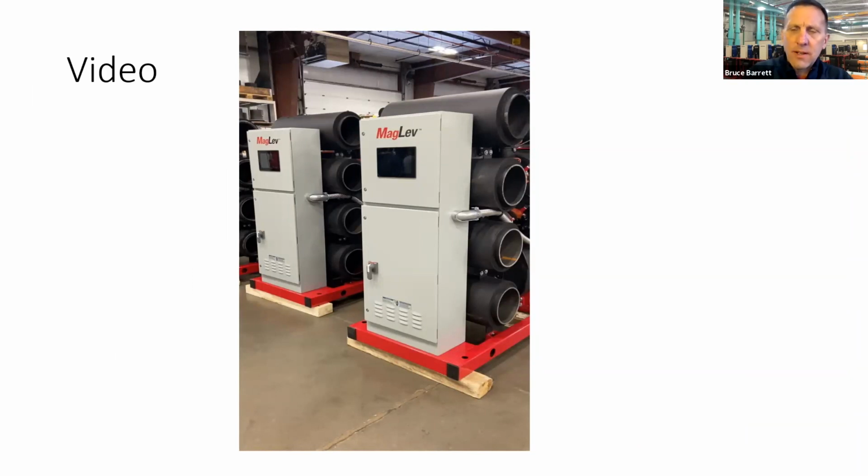So if you've got a 1,000-ton machine with a 10-degree delta T, that could be 2.4 GPM per ton, 2,400 GPM. But one of those modules, I can turn down to one module's worth of flow. So it could be 80 GPM out of your 2,400 GPM. So tremendous turn down potential on the flow and your pump side.